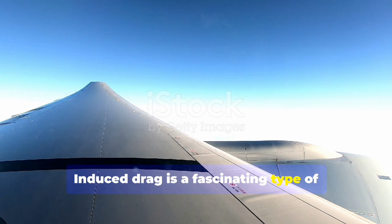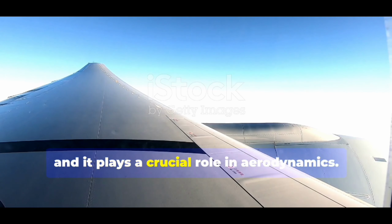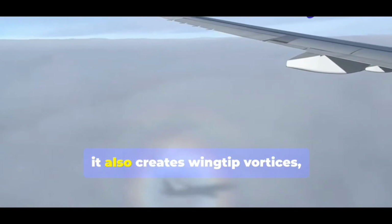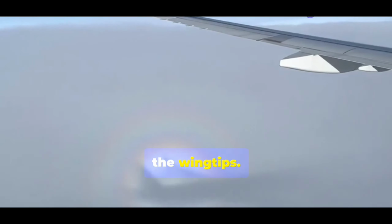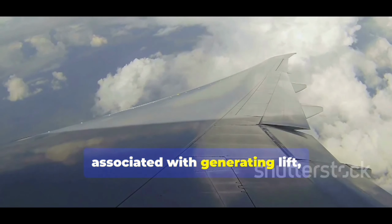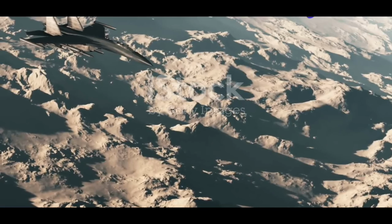Induced drag is a fascinating type of drag that is inherently linked to lift. It plays a crucial role in aerodynamics. As an airplane generates lift, it also creates wingtip vortices, which are spirals of air trailing from the wingtips. Induced drag is a drag penalty associated with generating the lift. It increases with the amount of lift produced.